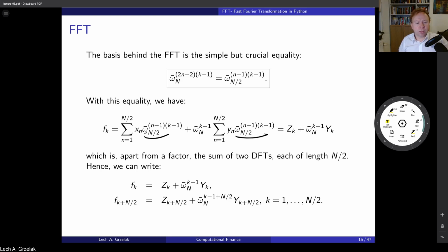So then you see that once we divide our summation into odd and even terms, with x_n and y_n, our weights are now given the same way, in the same formulation. This allows us to represent this problem as z_k plus the additional correction term that we have just rederived from here. Of course, keep in mind that this omega_n is exponential, so everything can go outside if we take a product there.